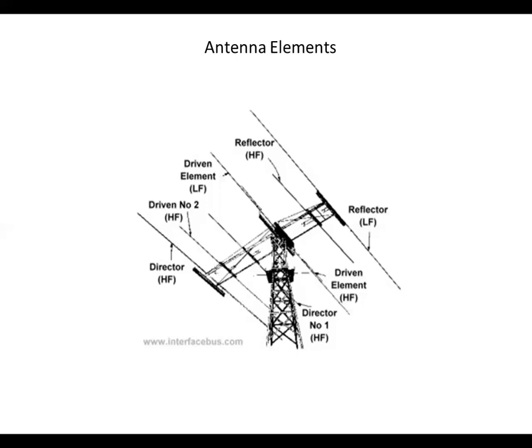Got it. Okay. Now, if you look at some of the Yagis, they may have 6, 8, 10 elements, and that's where you're only driving one of them, and you have a bunch of reflectors and then one director on the backside, I think it is, and that focuses more and more energy into the direction you want to go.